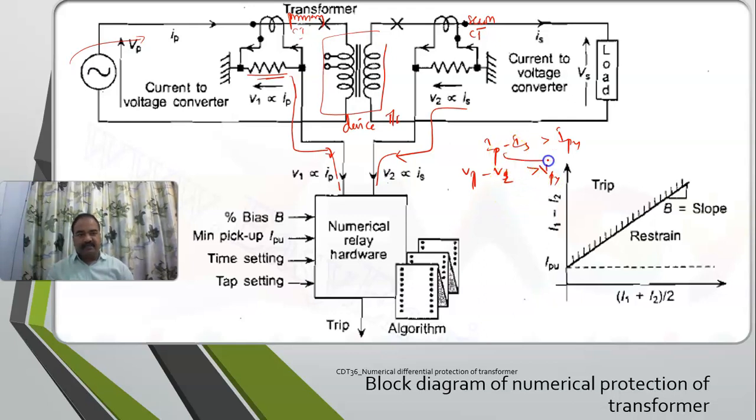See, you assume that it is a current, so it is just like delta I is greater than your IP. If you carefully see in the last slide, you have already seen this is the fundamental concept of your overcurrent relay. So it is just like your overcurrent relay being modified in order to identify internal faults. So again you are supposed to have your pickup value, the time delay setting, your relay characteristics, etc.